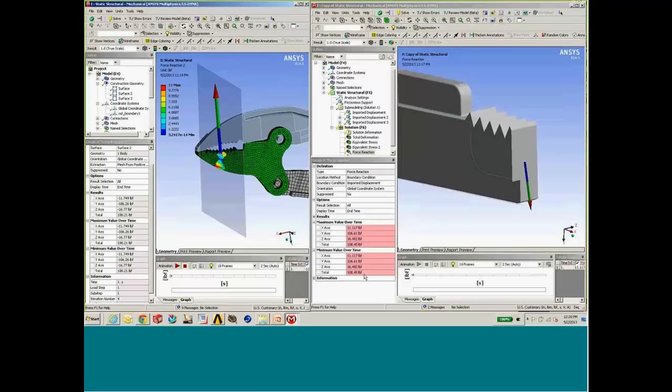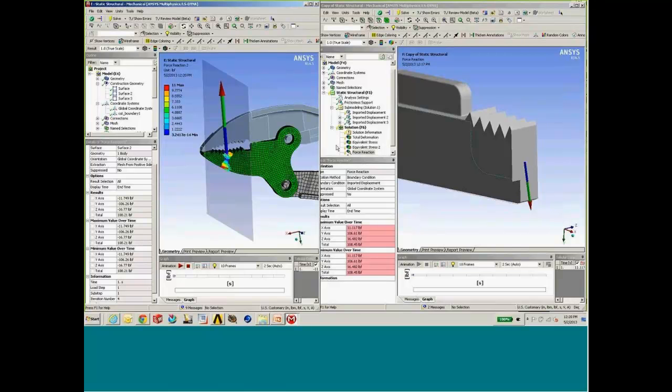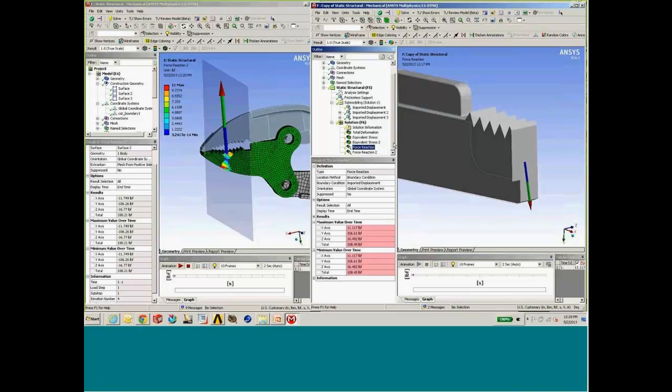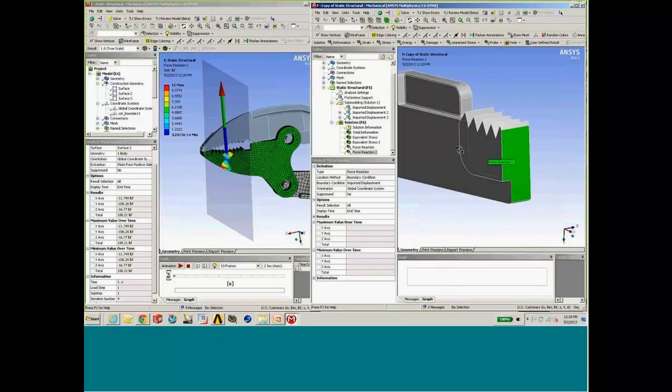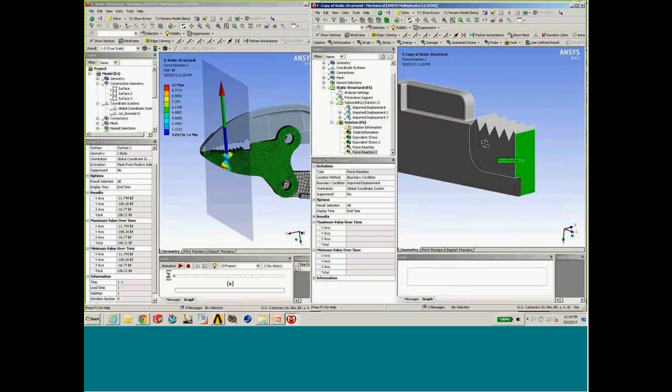We don't need to worry too much about moving that cut boundary. So that's the best way to check and make sure your forces are summing or adding up correctly on both the submodel and the global model. We can also compare stresses on those locations. So let's go back here. Actually, I invalidated my solution, so I don't have a stress response.